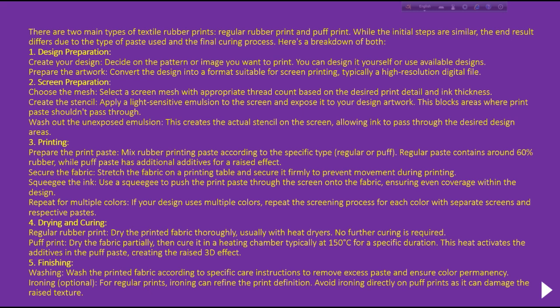Then is printing. Prepare the print paste. Mix rubber printing paste according to the specific type. Regular paste contains around 60% rubber, while puff paste has additional additives for a raised effect. Here, the function of additives is to raise the print.